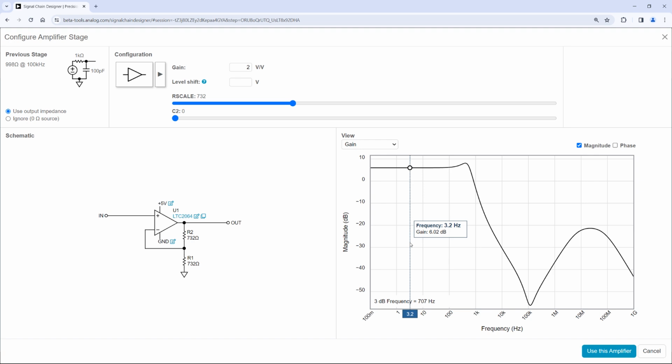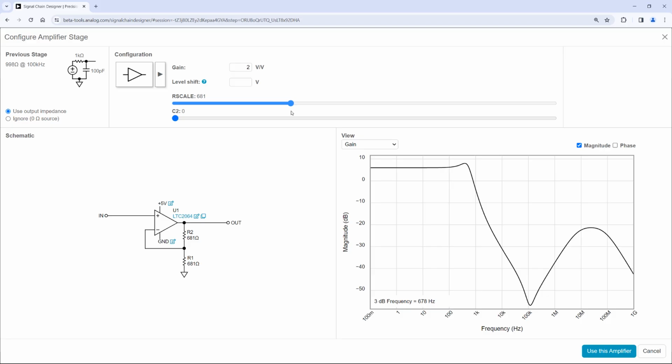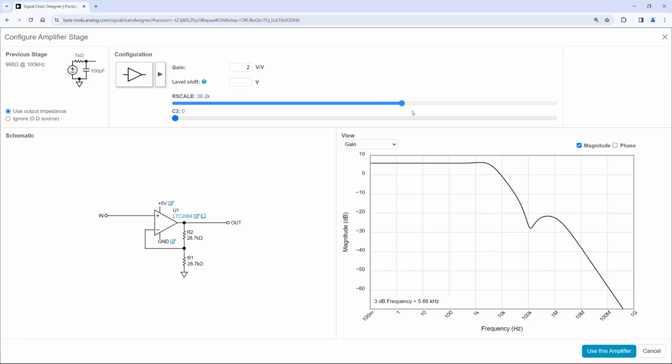What you really want to take away from this is it's not a good idea to use the part in this region. You're probably going to get a bunch of distortion. The part isn't really designed for it here. So when you see that the bandwidth is dropping way below what the part is spec'd, try to avoid that and work in the region with the higher resistors. When you're using a low power part, be aware of that behavior.